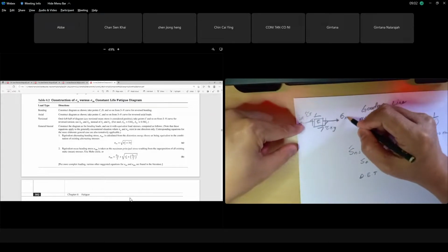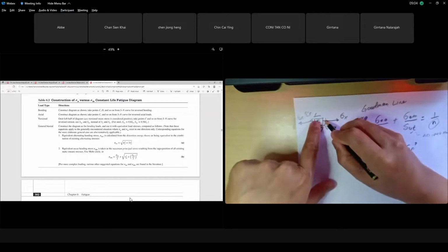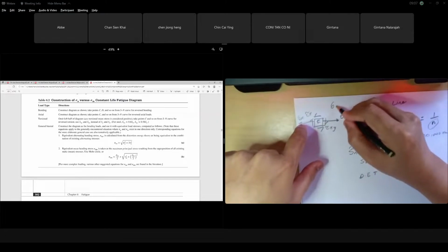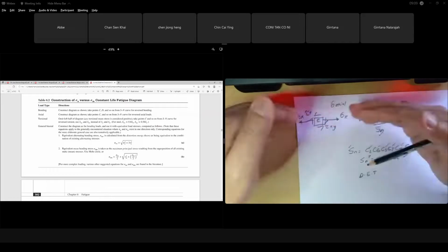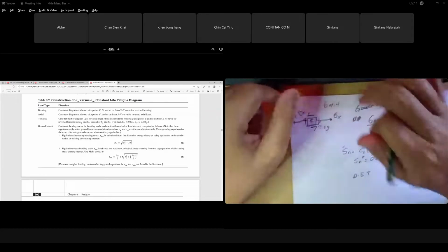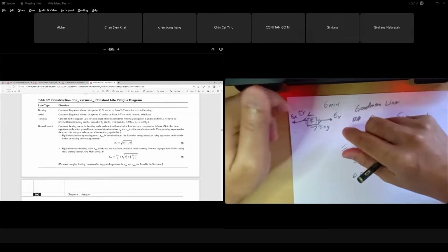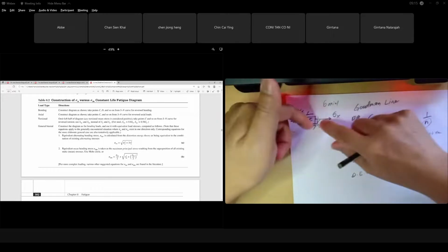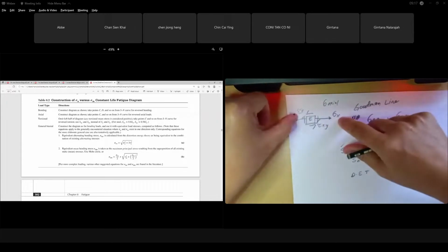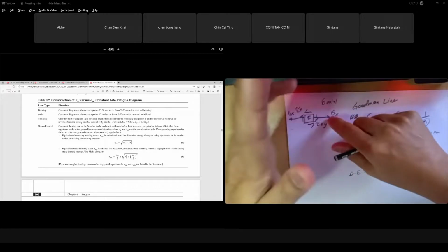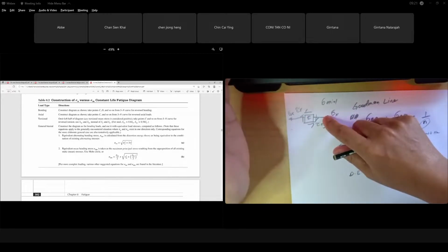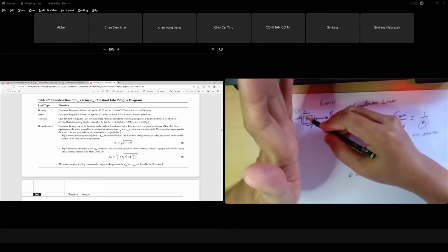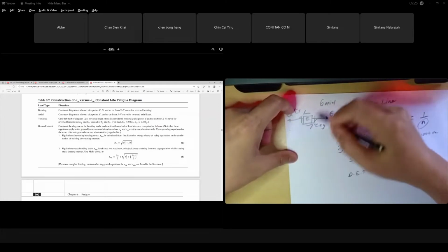Rarely do we have more than that. Sigma x, normally in our case of a shaft, is based on bending. Sometimes we have axial stress combined with bending, because for the sample problem we will discuss later, we have a combination of axial and bending stress, which gives your total sigma x. But we always have torsion at the point of consideration. Sometimes we have torsion, sometimes not, but in most cases at the point we look at, we have torsion. This is what we call biaxial stress.